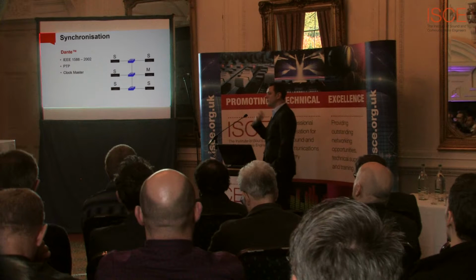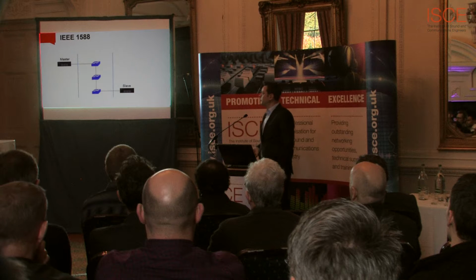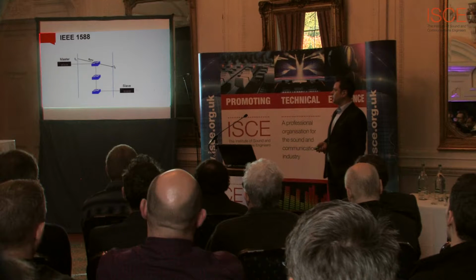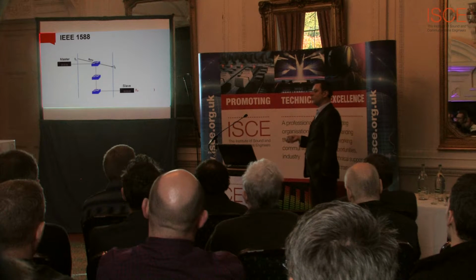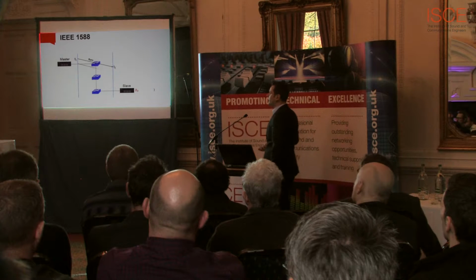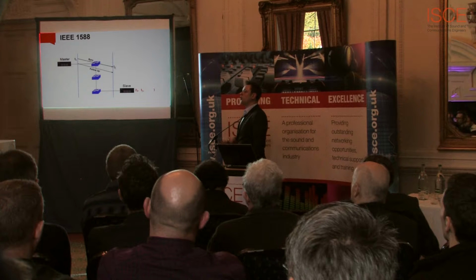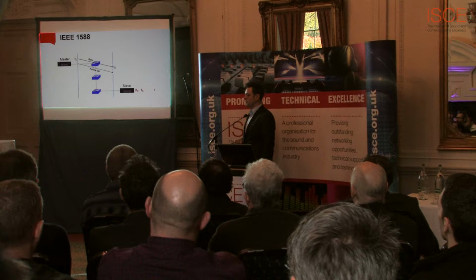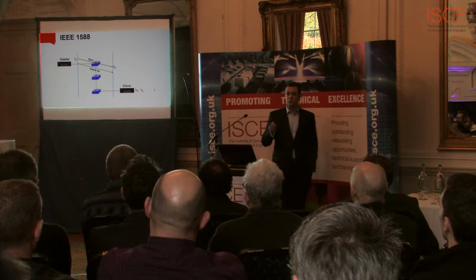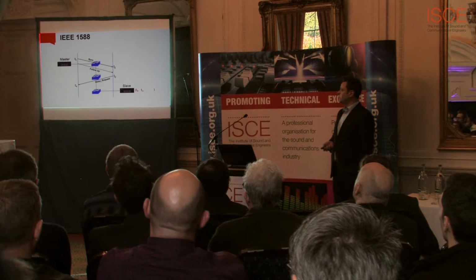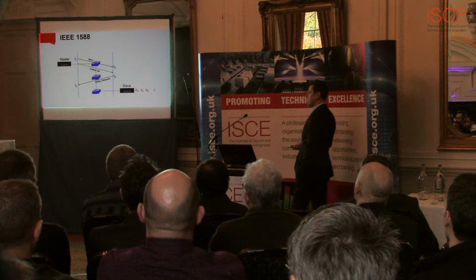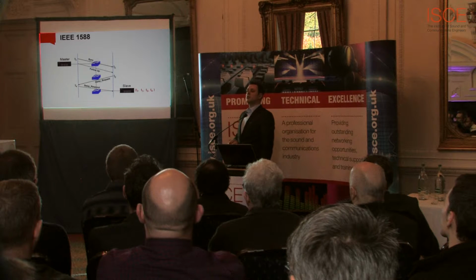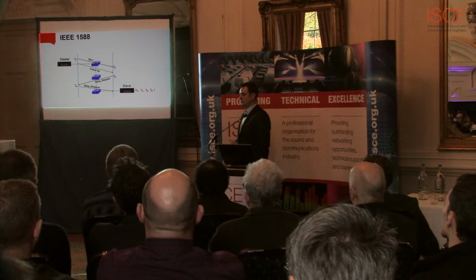But rather than sending 750 packets a second down the network, about once per second, the master will send one packet to the slave. Now the slave knows what time that packet arrived. Shortly thereafter, the master sends a second packet with an exact, precise timestamp of when the first sync message left. Now the slave knows times T2 and T1. The slave responds and sends a delay request at time T3, so then he knows what time T3 is, and the master replies with the time that he received that second message.